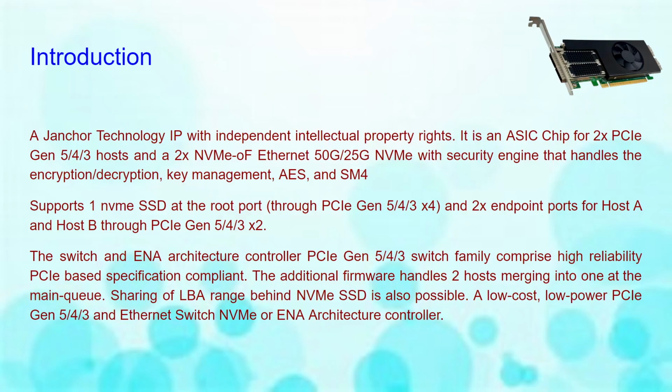It is a chip that can control two hosts PCIe Gen 5, 4, or 3, and two Ethernet 50G or 25G with a security engine that handles encryption or decryption and key management. The PCIe hosts are handled by the ENA architecture controller, while the Ethernet is handled by the switch of the Orca S1100. This chip is also low cost and low power.